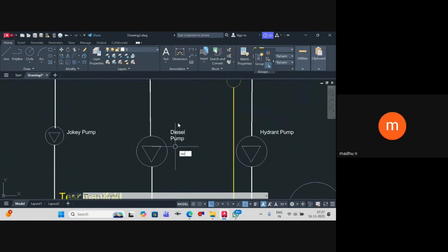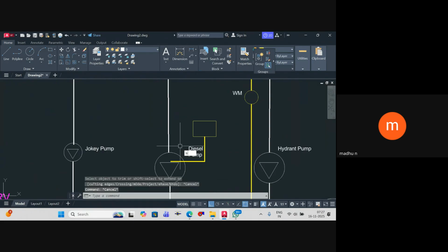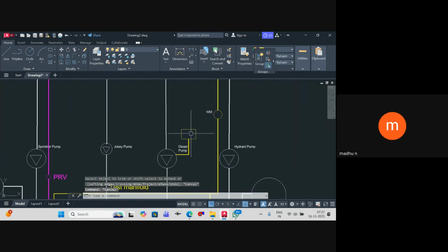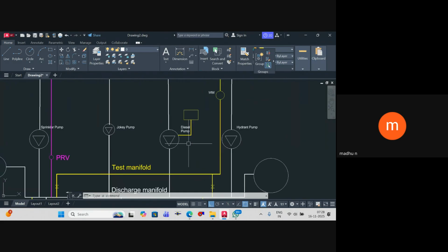How do you design its capacity? You have to take 2 hours of its running time. You should have the capacity. It depends on the efficiency of the diesel, so minimum 2 hours is what you have to store inside your tank. Storage capacity 2 hours. That is also there in the IS code. I'll share you a screenshot of that. It's clearly mentioned, according to your hazard, whether it is 2 hours or 3 hours. In 99% of cases, 2 hours should be sufficient. Understood? Anyway, it's there in the IS code, and it's clearly given for diesel.